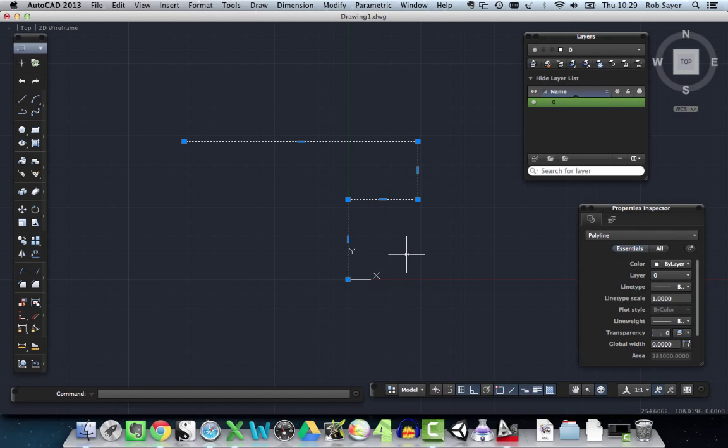So there are different ways of doing it, but basically the whole key to this is to start to become comfortable with drawing lines of a particular dimension in a particular direction, and also to use the snap, object snap, and also the Ortho Mode in order to make sure that your lines are at right angles to the drawing. Hope that's been useful. I'll see you soon.